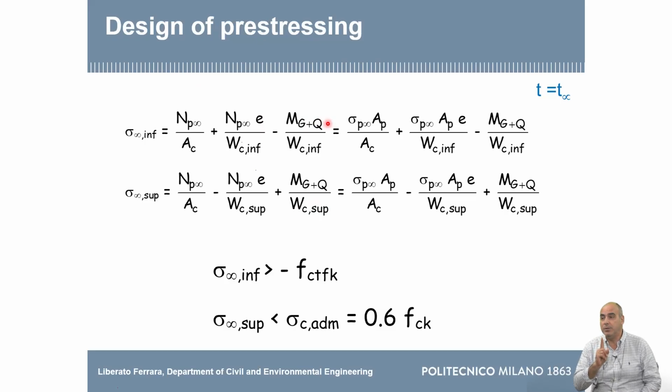But there is another thing which has changed. Here I put, and it is not a misprint, NP infinite. In the previous case, I put NP 0. The pre-stressing force has changed. Yes, the pre-stressing force changes because we have what we call the pre-stressing losses. We will see what they are due to, but for the moment, let's accept that they exist. Then we will explain what they are due to and how we calculate them. But provided this, we write our equations.